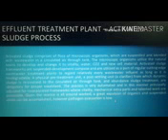To treat almost every wastewater as long as it is biodegradable, a physical pre-treatment unit, a post-settling unit from which active sludge is recycled to the aeration tank, and adequate sludge treatment are obligatory for proper treatment. The process is highly automated and is mainly suited for integrated systems where energy, mechanical spare parts and skilled labor are available. Given the reactor is well operated, a high removal of organics and suspended solids can be achieved, however pathogen removal is low.